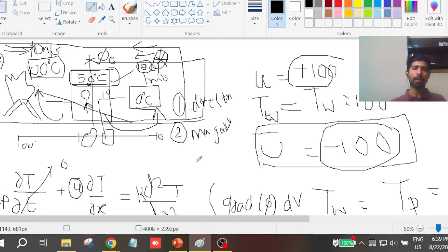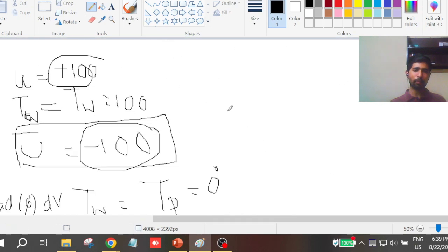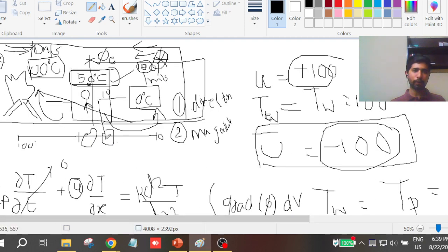Now you can go on with that. In general, how we derive the upwind scheme, I will discuss during the questions. But just remember that you have to do such upwinding, taking the influence of the temperature in the upstream direction.